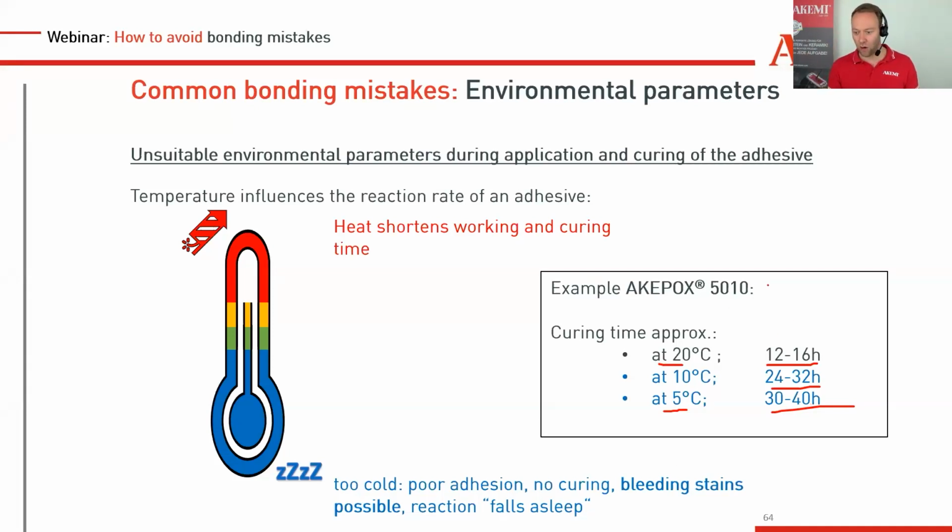Usually with an Archibox, you have a working time of 20 to 30 minutes. It starts to get gel-like after 1 hour, maximum 1.5 hours, so there's no moving into the stone anymore. But at 5 degrees, maybe the glue stays liquid and soft for 4, 5, 6 hours. There's a lot of time where these polymers can start moving into the stone and can cause a discoloration.